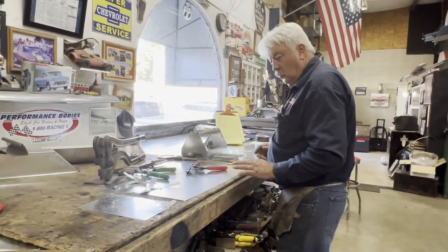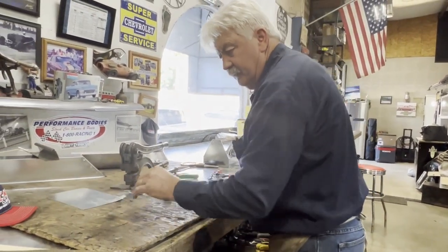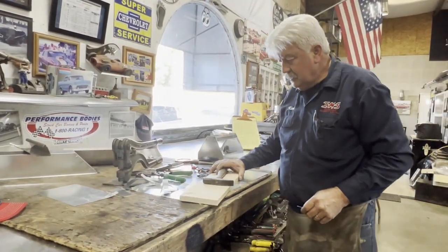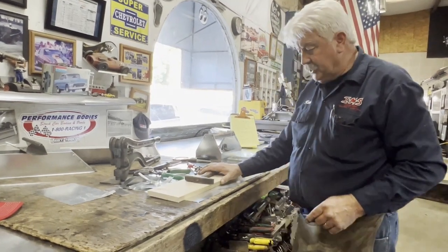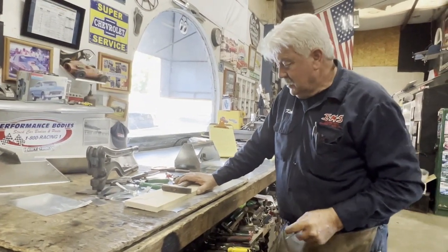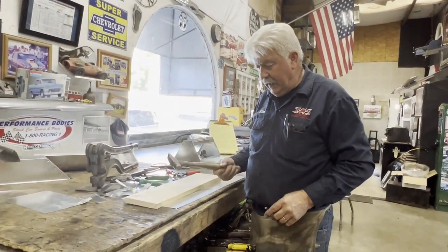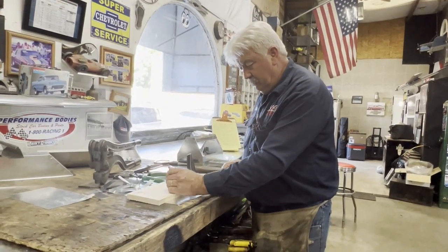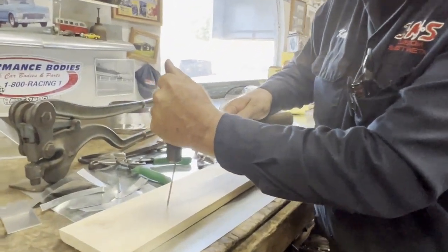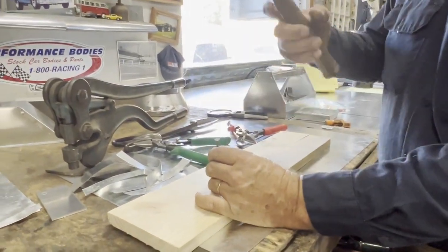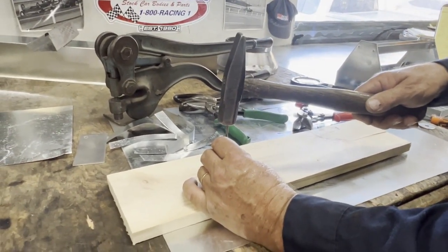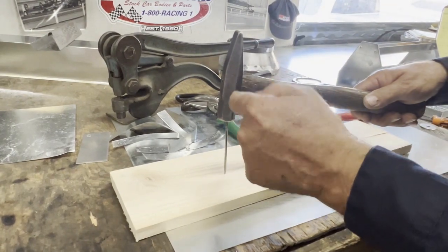So, another thing I wanted to go over with, we always want to give ourselves the best chance of going home at the end of the day in awesome shape. So one thing I want to point out with a hammer, I would never put the nail here, put the hammer, and then try to push that nail through the board. So what we're going to do is we're going to use the inertia by the moving hammer, and we're going to let that inertia drive the nail in.